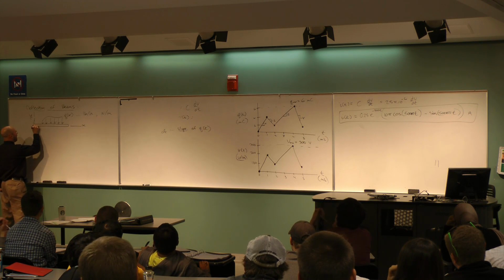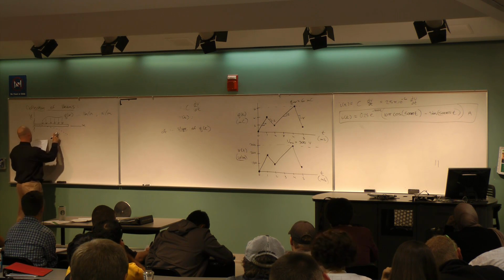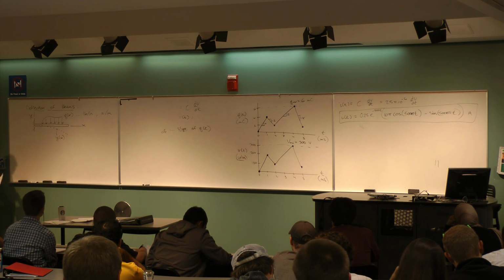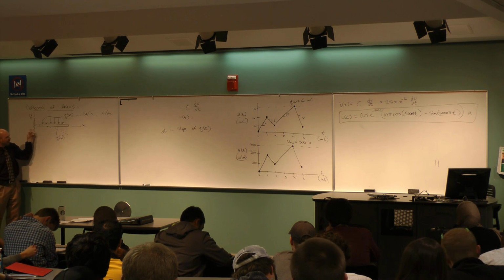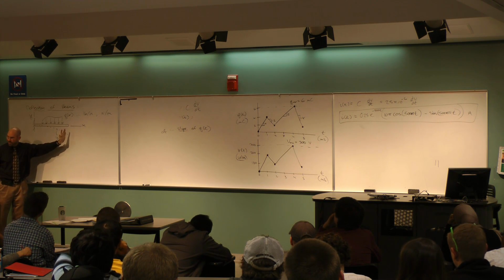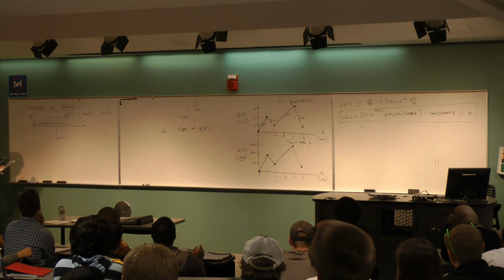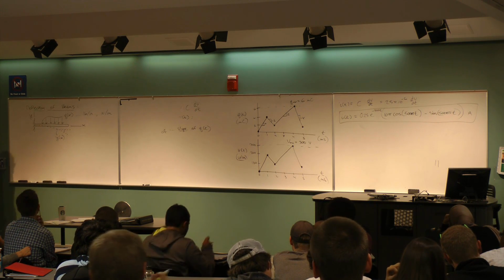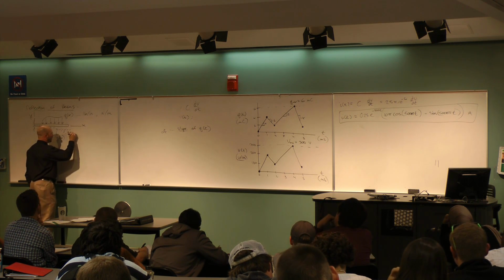So here's the idea. This thing loads up, and the center of the beam will deform in some way. This deflection right here is y as a function of x. As this thing moves in the vertical plane, every point along the length of the beam has a new y coordinate. That y as a function of x gives me the deformed shape of the beam, the actual shape. So at any given point on the beam, I can identify an angle that this thing makes, and that angle I'm going to call theta of x.